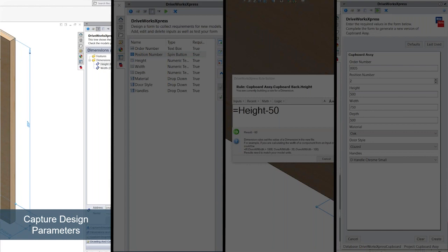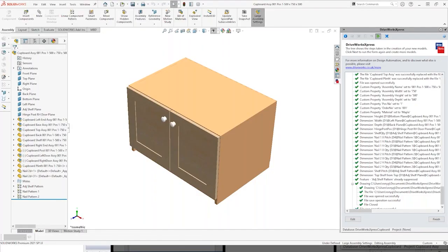This is a simple process. You basically recognize out of all the components in your assemblies, which ones I need to make changes to. And then I also want to make sure I capture any dimensions that I want to modify, any features that I might want to turn on and off, suppress and unsuppress, maybe some file properties that I want to control, like material, for example. But the goal is to capture all that information. That's the first step. Let's jump back into SOLIDWORKS here.